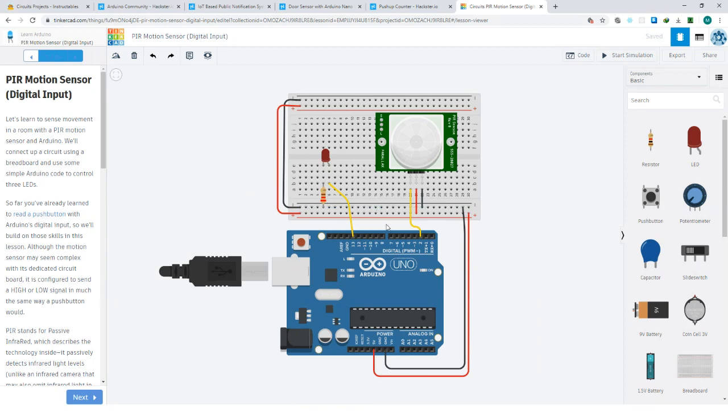I think that's very clear. Remember the pins we are talking about, one is positive and the other one is negative. One is put on the Arduino: it takes the 5 volts of the Arduino, the one in the middle, and the one at the corner always takes the negative or the ground. You put it on the ground and then you're good to go. So if somebody comes closer, or movement takes place, then this particular LED will light.